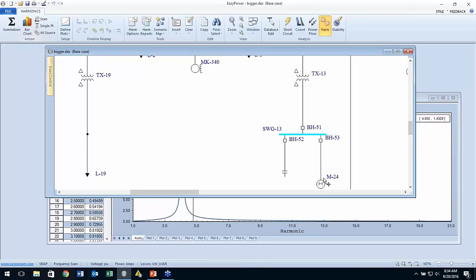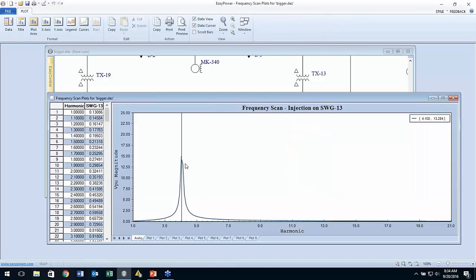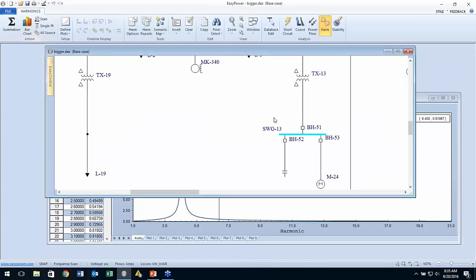But as soon as we're starting to put in a VFD that has any content in that particular range, then we may have to contend with the potential harmonics issues that are going to potentially arise because we have frequencies in that resonance point.